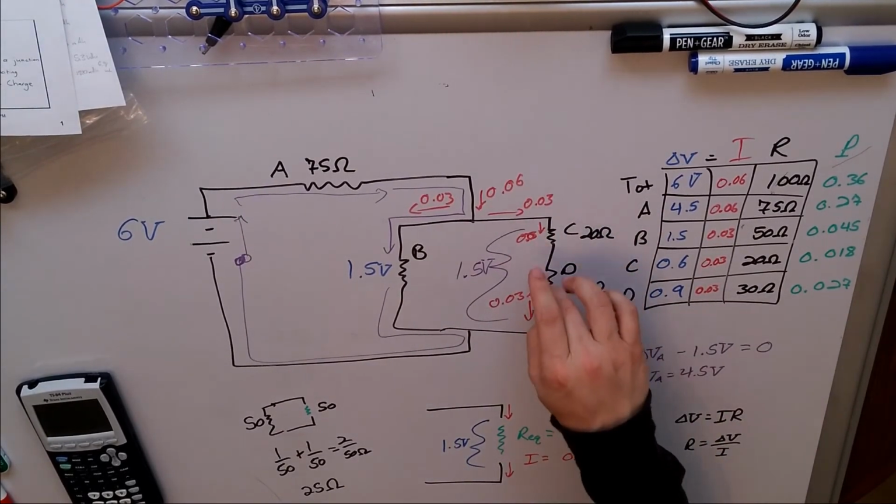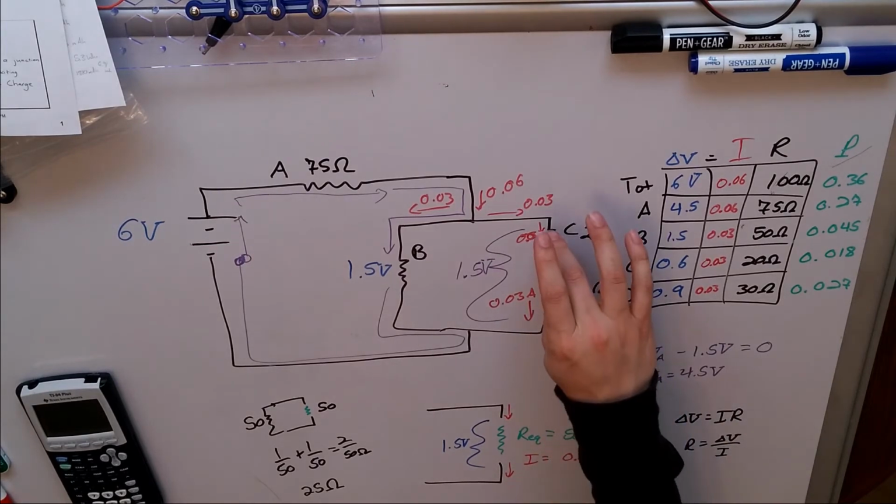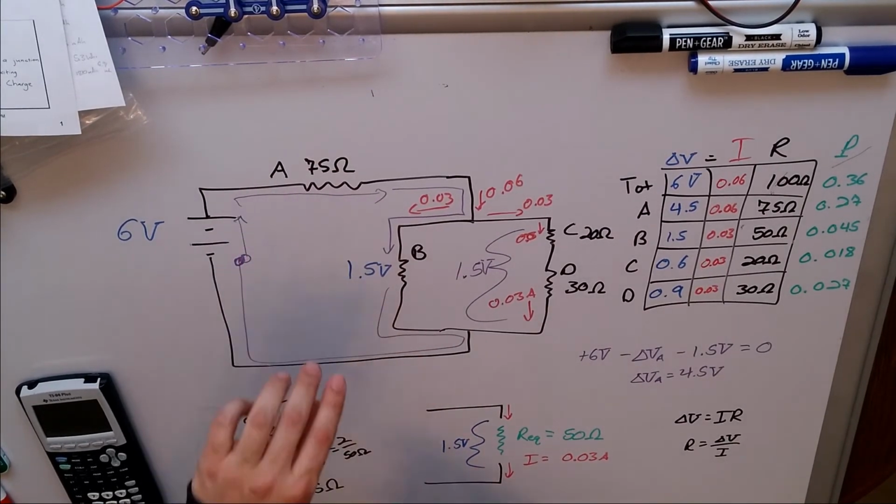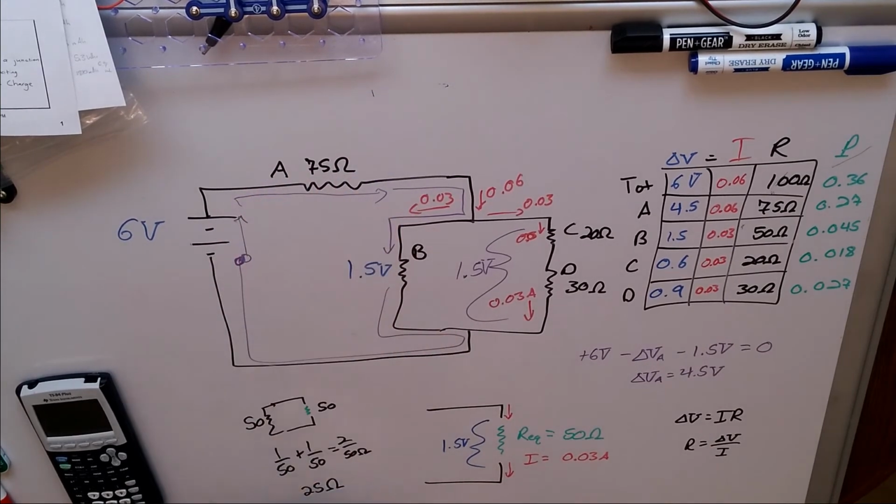Your currents, however, are not used up, not raised, not lowered. They continue and they stay the same. Each of these have different ways that they interact with components. Your delta V's will change, your currents will stay the same as they go across one of the components. Charge is conserved, and because energy is conserved, we have each of these reducing the height so that we can release energy from it.